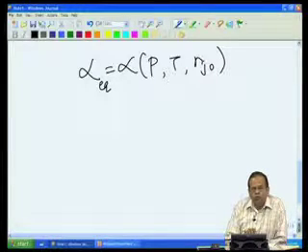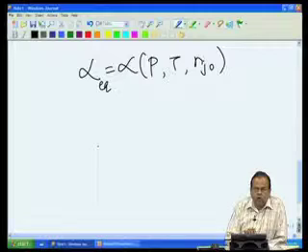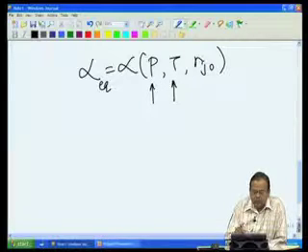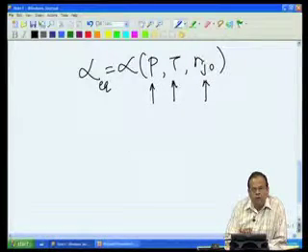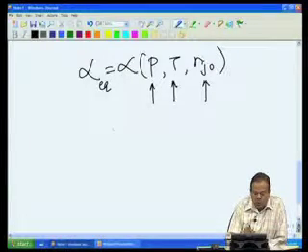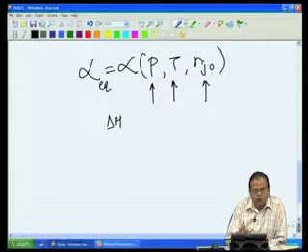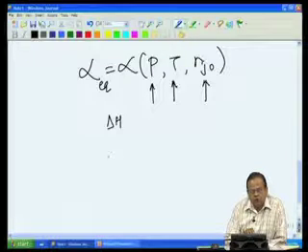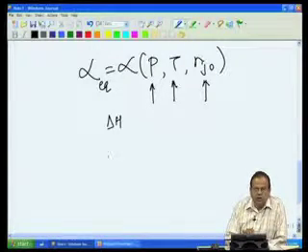Now, if we want to increase this equilibrium conversion, so that we can realistically get higher conversions in our reactor, then we have to play around with the operating conditions such as pressure, temperature, the composition of the system and so on. And this largely depends on the heat of reaction. So, the temperature effect, for example, is that if the reaction is exothermic, the equilibrium conversion decreases as temperature increases and so on.